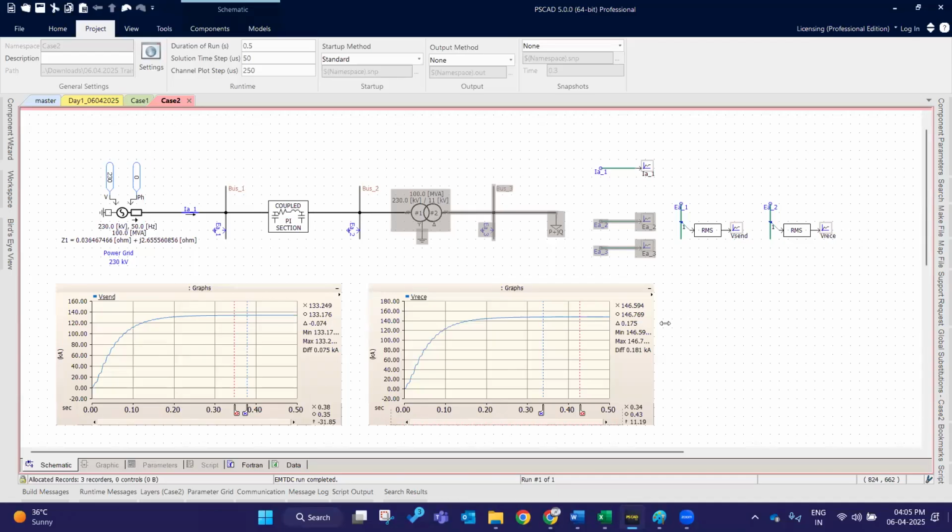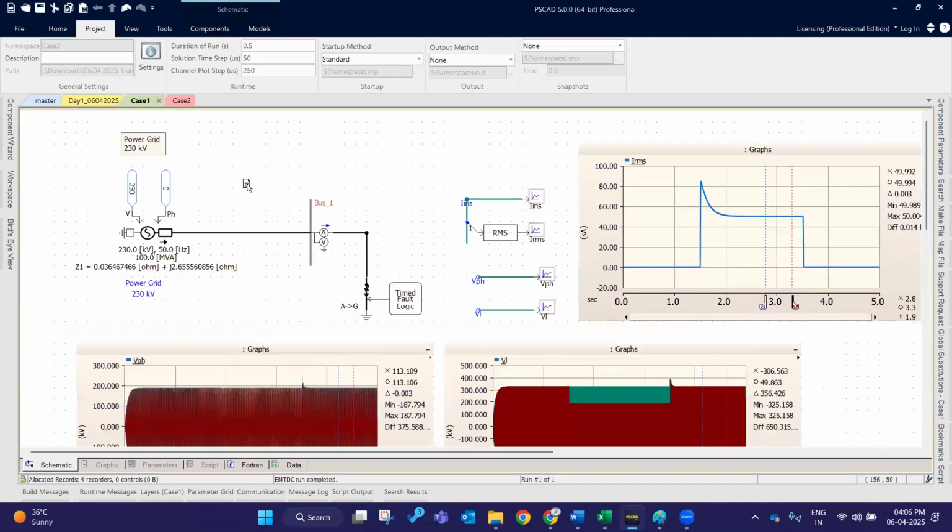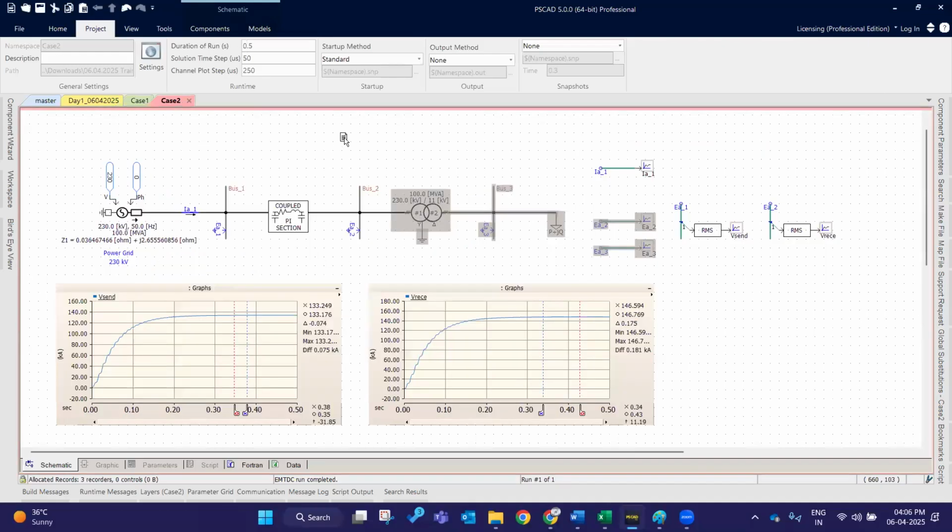Then finally, we started the source modeling with the data. With the source, I showed how to model the source and validate the source with some calculations. And we have validated the same in our PSCAD also. So after that, we have created a simple SLD network. So this is how we should configure everything in PSCAD.